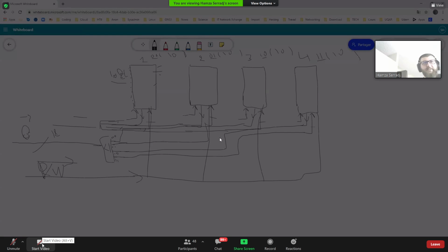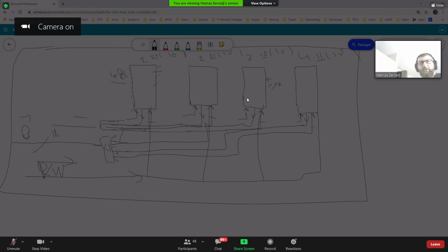So we send that signal of 0 or 1, and we enable which bus. Okay, so we select the chip here. Let's go to 1, 0. Okay, 1, 0, we're here. And after the 10 bits, we select which location we are at, between 1 and 1024. And we had here, for example, 0. So this bus will be enabled and the data will go out. And this is a memory chip of 4 kilobytes. If we take this principle and double it on the other side, we have 8 kilobytes. So it's just a small chip for a small amount of memory.